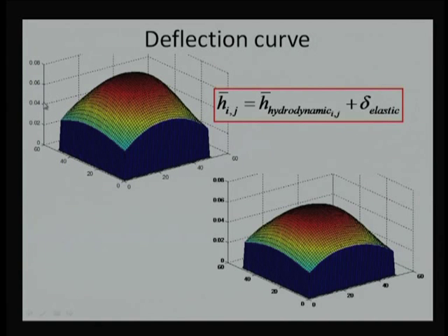You can see here it is crossing 4, reaching maybe 5.2 or something like that, 0.052, while here it is much lesser than that, even 0.038. So, there is a variation. What this means is that we need to account for this variation in film thickness, so that we can find the right results, otherwise it will be problematic.